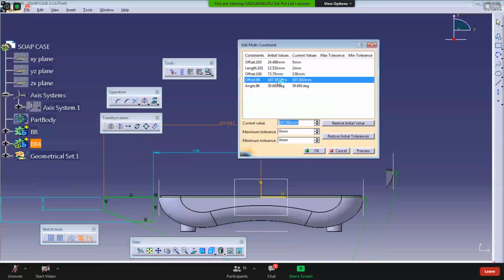So the command we are going to see here is the intersect command. There are three Boolean operations as per our last discussions: add, remove, and intersect. We have used add and remove so far. Now intersect is a new one. Intersect will generate the common portion between the two features, and you will get the resultant body. Let's see here, this size is 151.